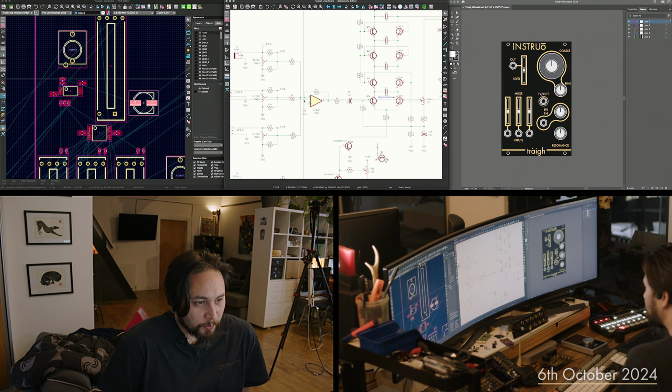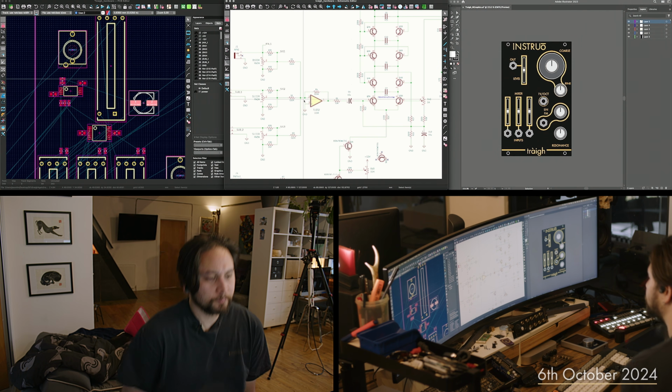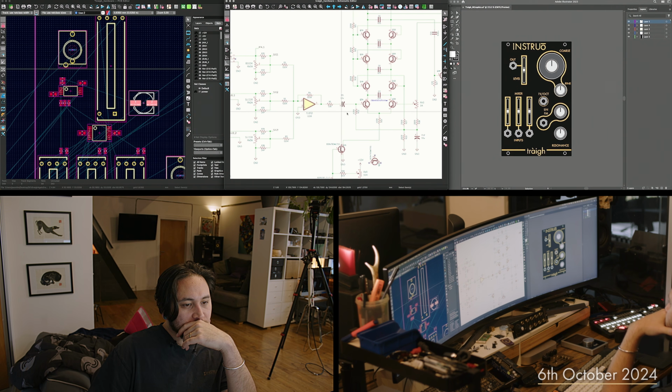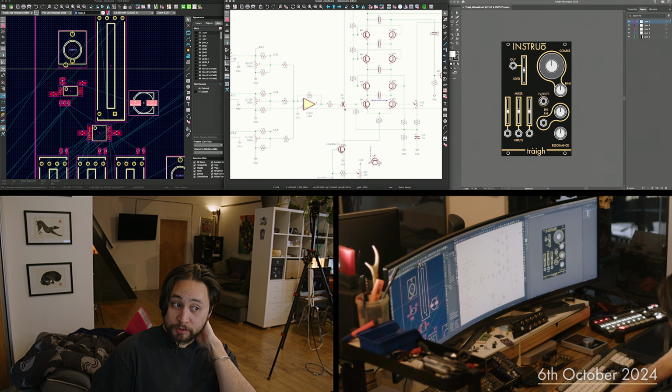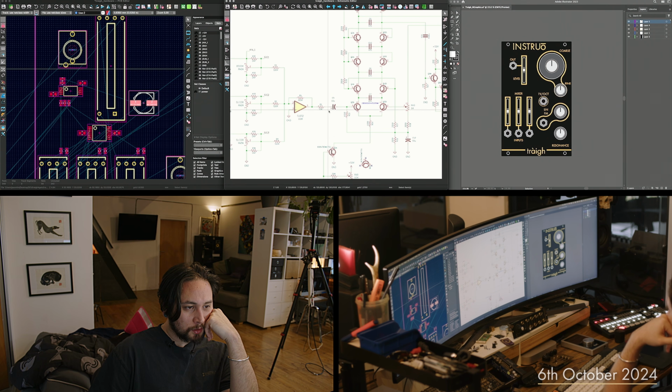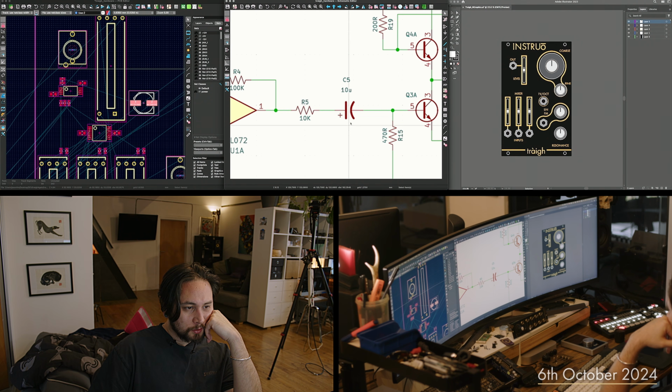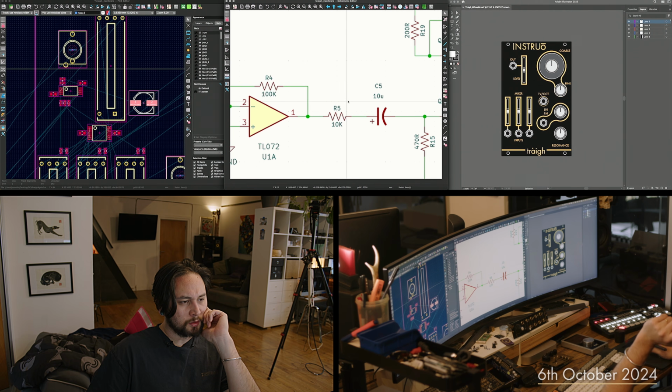There's one thing I've wondered about this. That's AC coupling, but it's a polarized capacitor. Arguably this should be pulled up positive with a DC offset, right?